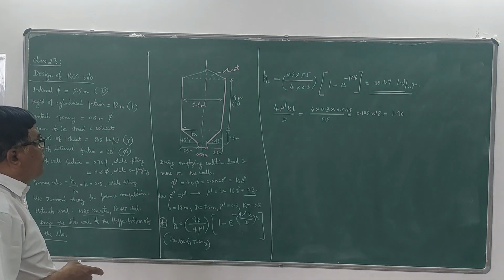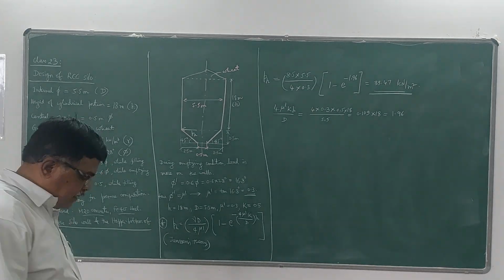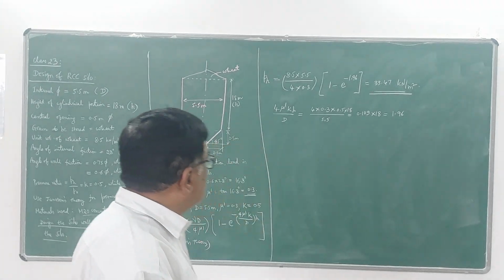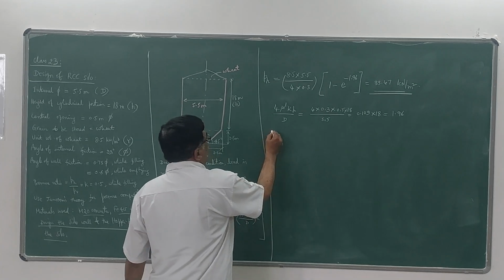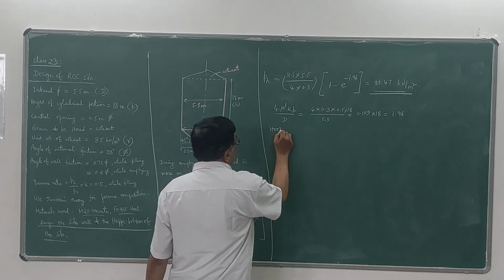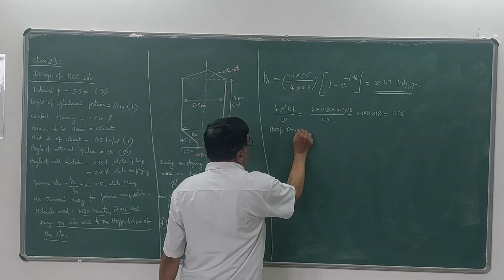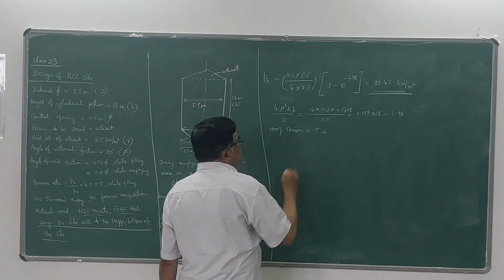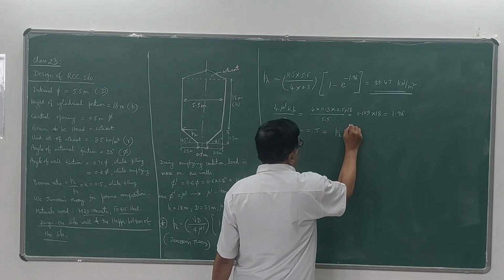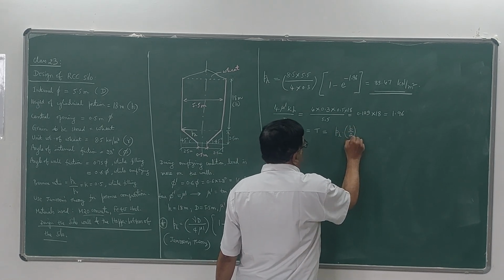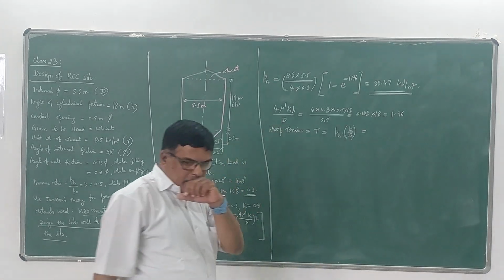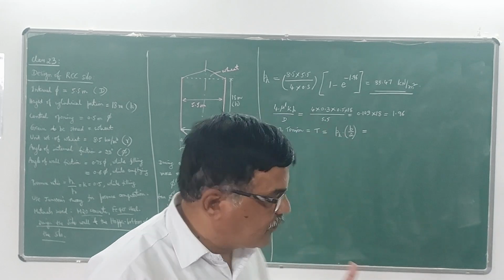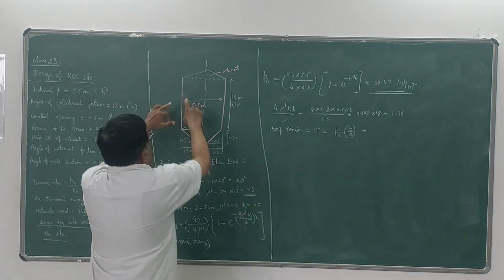So once this value of pH we obtain, then what we have to do here is calculate the tension, direct tension. We have hoop tension we have to calculate. Hoop tension, I have given the equation. Hoop tension is given by T is equal to pH into D by 2. So here D is nothing but the width, the width is nothing but the diameter.